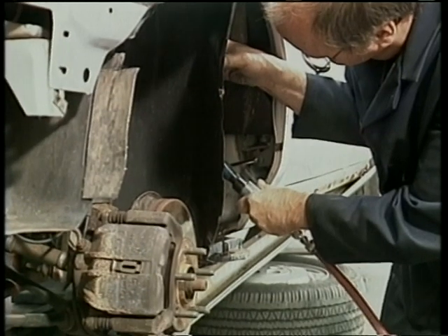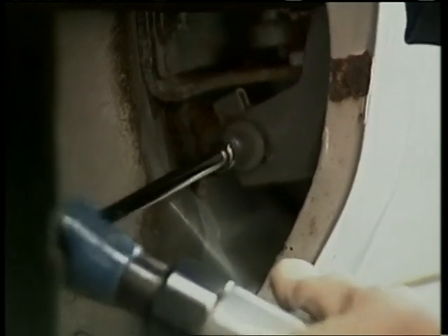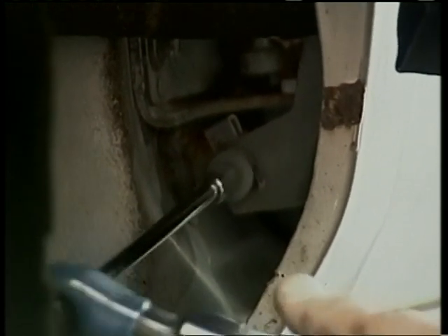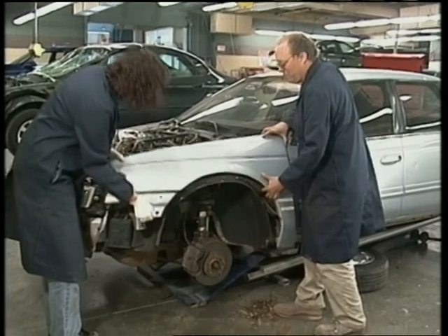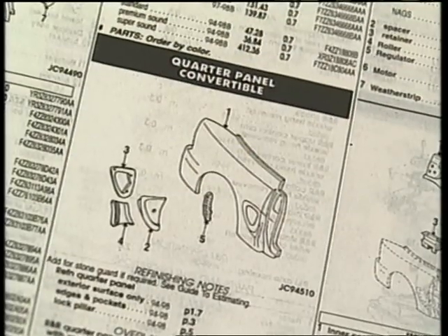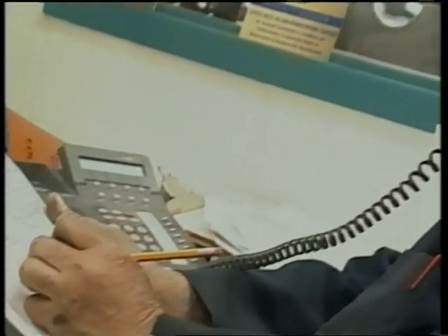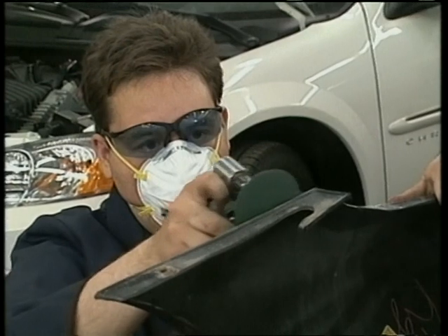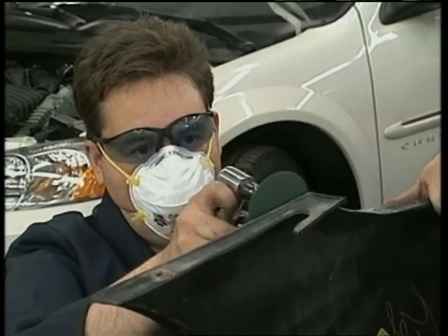The crash book explains what labor time does and does not include. For example, in the crash book, replacing a fender includes removing, installing, and aligning, but it doesn't include installation of antennas, pinstriping, or application of decals. That's why the labor reported in crash books should only be used as a guide when estimating total repair costs for a vehicle. Refinishing time must also be factored into your estimate.